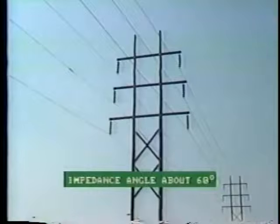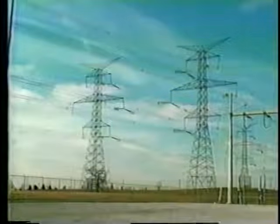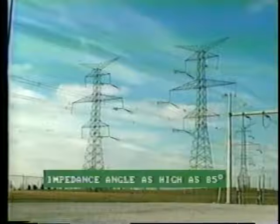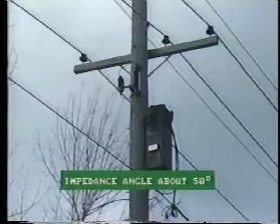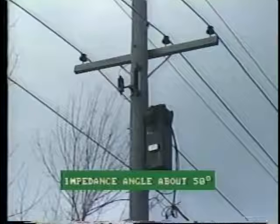The line impedance predominates, and for a 115 kV transmission line, this is usually about 60 degrees. High voltage lines, 230 kV and up, may have impedance angles as high as 85 degrees. Conversely, low voltage distribution lines usually have a line impedance angle of about 50 degrees.